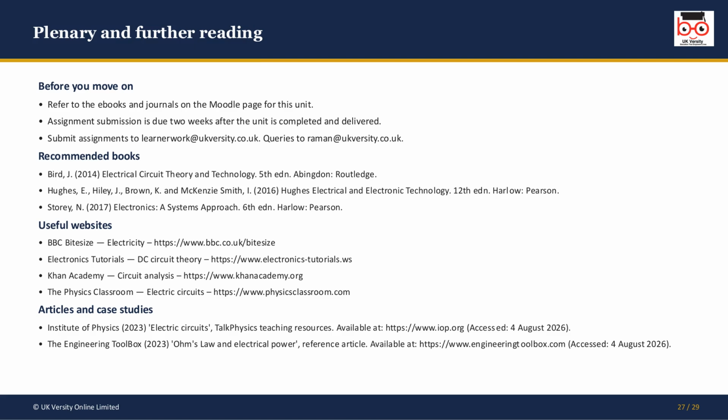When an object is balanced, in other words, in equilibrium about a pivot, the total clockwise moments equal the total anti-clockwise moments. This principle applies to seesaws, beams, and balances of all kinds. Each moment is force times perpendicular distance, so you set the clockwise sum equal to the anti-clockwise sum and then solve for whatever force or distance you're missing.